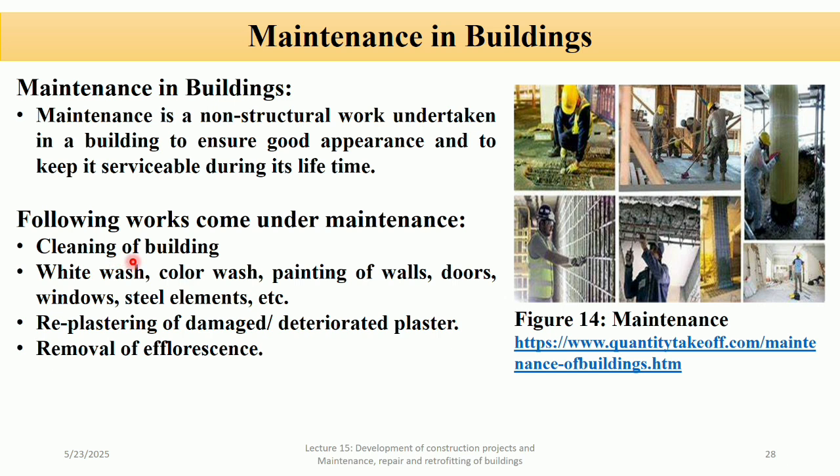Regular cleaning to remove dust, dirt, stains, etc. Whitewash, color wash, painting of walls, doors, windows, steel elements, etc. A fresh coat of paint on walls, doors, window steels, etc. to maintain appearance and protect surfaces. Replastering of damaged plaster. Reapplying plaster where it has deteriorated or fallen off to keep walls in good condition. Removal of efflorescence. Cleaning the white salt deposit that appears on walls due to moisture movement.